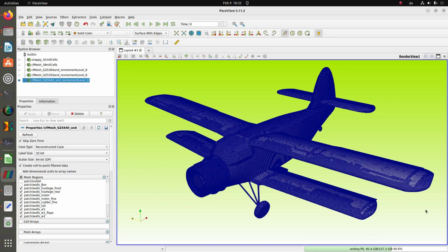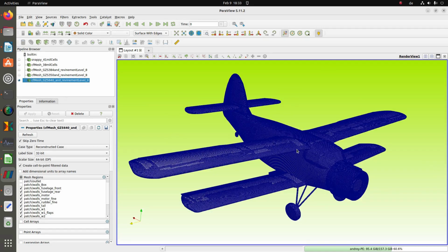This means that we set the necessary refinement level on each boundary of the airplane and reduced the number of cells to a minimum. If we had taken the geometry of the airplane as one body, we would calculate too many cells in total, because we would have to take the smallest cell size for the whole body.